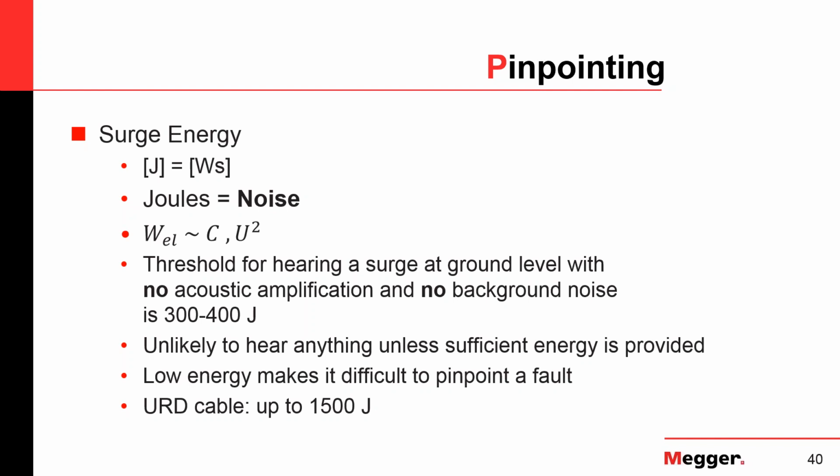Why is the creation of noise a problem? Or why are we doing this? Because the pinpointing devices can pick up either on the sound or the electromagnetic field. So the noise, or the thump, is the source of what you can pick up then to pinpoint the fault.